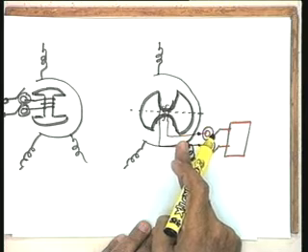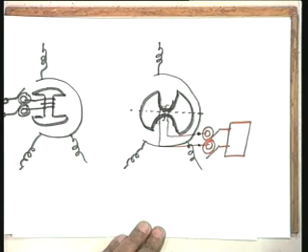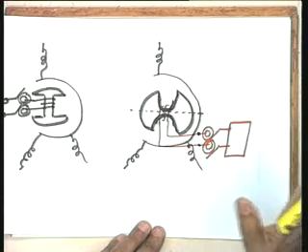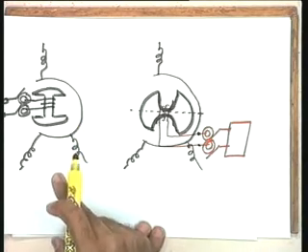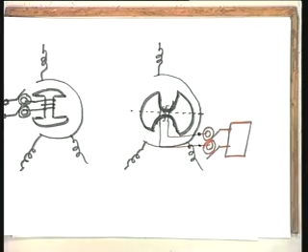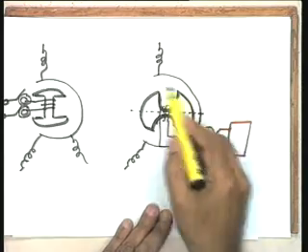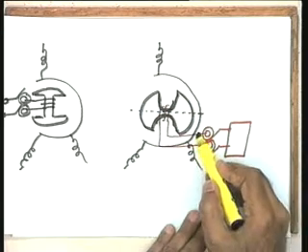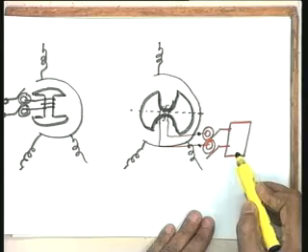This requirement is not that stringent in the earlier case, and therefore in the earlier case you can have a dumbbell construction. No one prevents you from taking the cylindrical construction there as well, but probably we save in cost, and that is why in the synchro transmitter, that is in this particular machine, we can go for a dumbbell construction. While the construction has to be more accurate here, the rotor has to be more cylindrical here, so that the impedance at these particular points as seen by the signal conditioning device is constant.